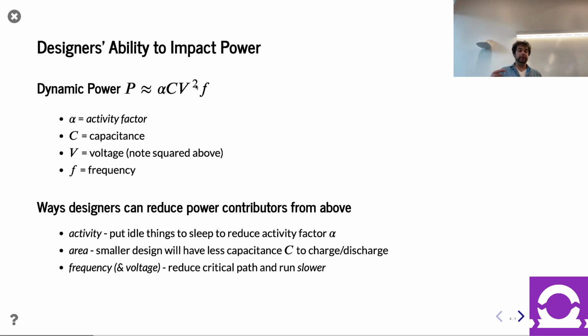And also it's worth remembering that if you change your area, you also change your power density. So things like cooling are often dependent on power density. In this case, I just told you you're doubling your area and you're halving your total power. That means you actually have 1/4 the power density. So that actually could be a very different landscape. Those are some very approximate numbers. It gives you a sense for what's going on there. So being able to run slower and lower the voltage is really, really nice when you can do it.